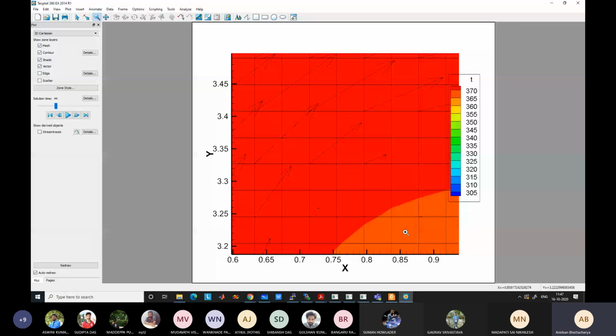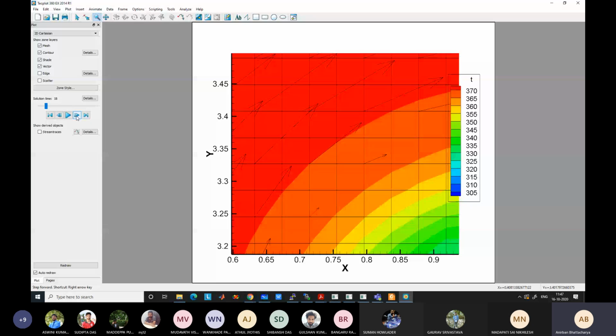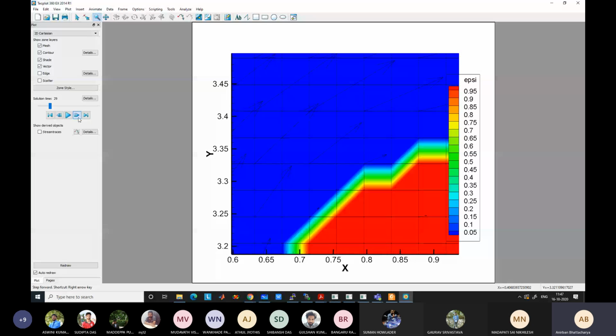Let us go back to some initial. Actually, take plot interpolates. That's why you will not be able to understand. Let me go to this plot only. This is better. So this is something called liquid fraction. How much liquid is there? Here liquid fraction is 1, meaning fully liquid. Here it is 0. And in between you see some center value, meaning it may be 0.5 or 0.3 or 0.2. So you cannot resolve the variation within the volumes.